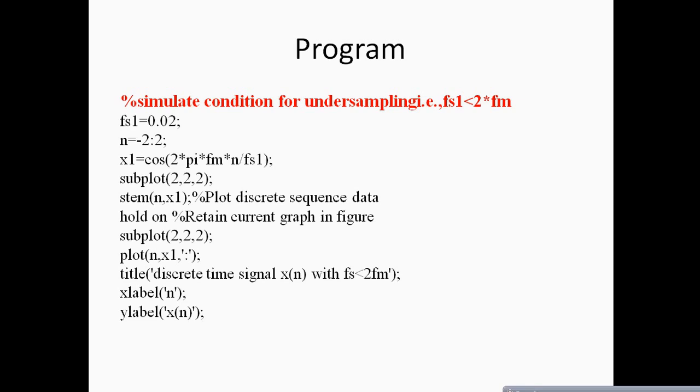Now after this, hold on, we'll be using the command which helps in retaining my current graph in the figure. So hold on helps the plot to retain, and then you'll be using that again in subplot. So plot n, x1 is your total, and all this works in coherence. That is, you are plotting, but your actual program part is only these 3 commands.